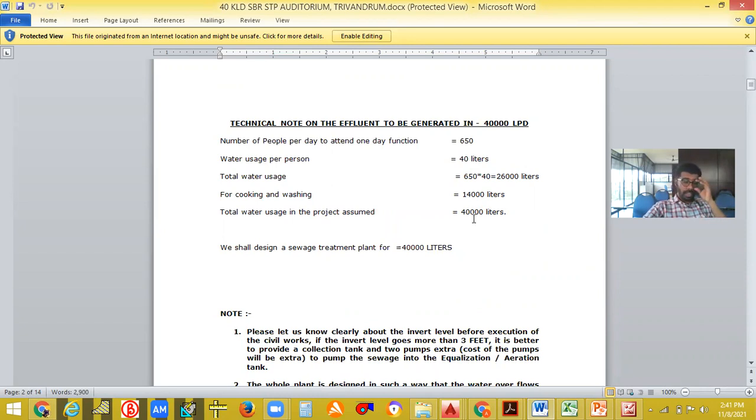Okay, it's much more than enough, because when we try to look for water storage capacity, this 40 liters is huge. So we don't really want 40 liters. I think almost 20 liters is enough for an auditorium. They have just taken a safety factor, multiplied, and given this. Afterwards, I called them back and they reduced the capacity of the